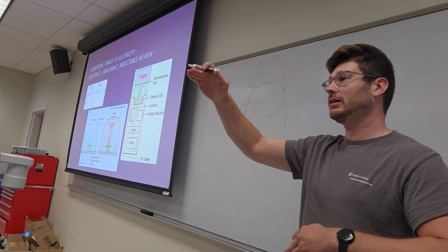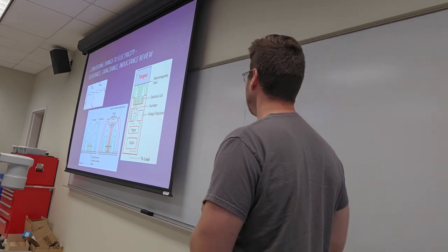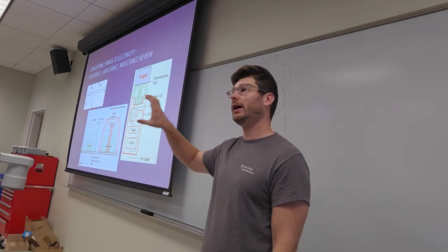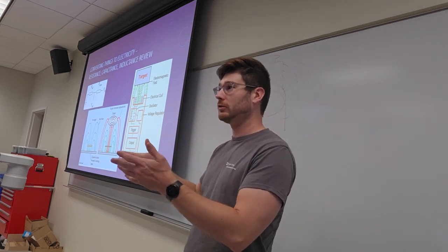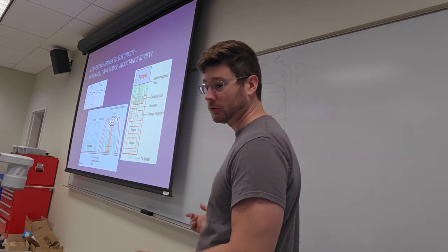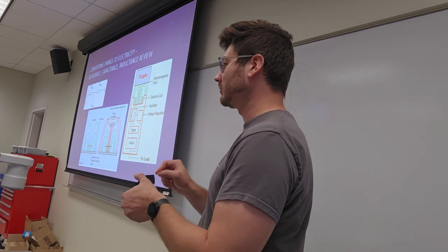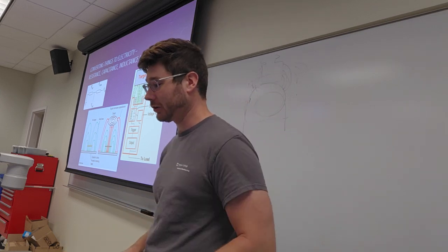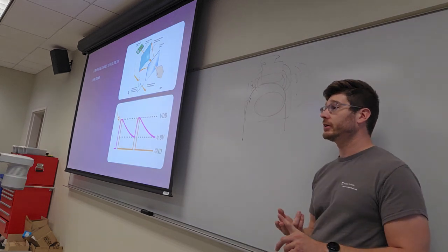So we're sensing inductance. If there's more inductance or less inductance, it's the presence of a large piece of metal, and then it can do whatever with that. The PLCs that live in the box next to the stoplight will register that inductive sensor and then do something with it. It's wired into the input of a PLC somewhere in that cabinet, right? Inductive sensor meets PLC. That's where the rubber meets the road in this particular case. Any questions about inductive or capacitive sensing?